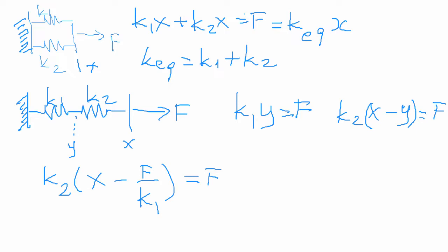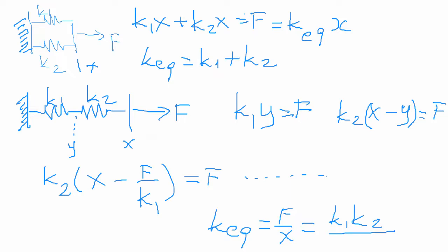If you solve it, you are going to obtain that k equivalent is equal to f over x, which is equal to k1 k2 over k1 plus k2.